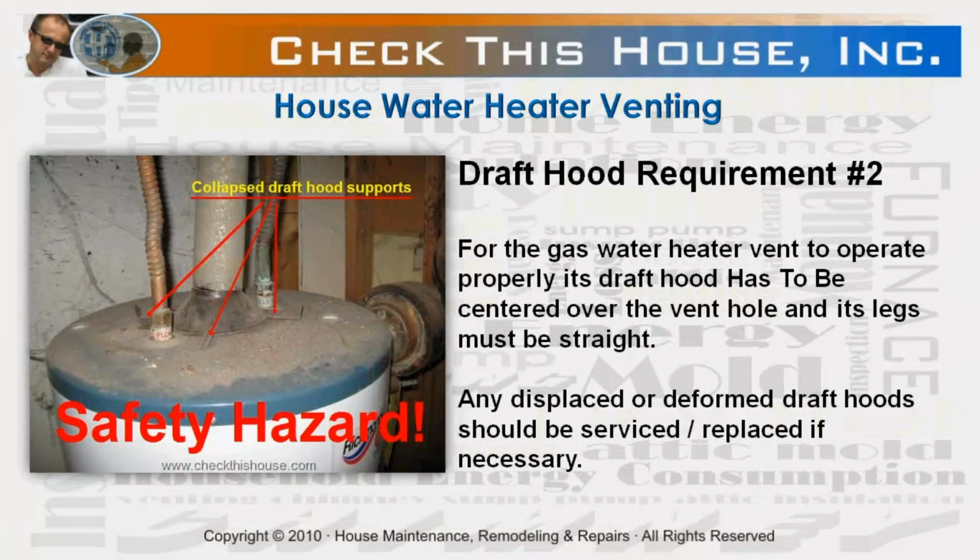The draft hood requirement number two. Notice on the picture how the draft hood has collapsed on its legs. This happened because the draft hood wasn't properly secured and it was supporting the entire vent pipe weight at the same time. Therefore, remember that for the gas water heater vent to operate properly, its draft hood has to be centered over the vent hole and its legs must be straight. Any displaced or deformed draft hood should be serviced and replaced if necessary.